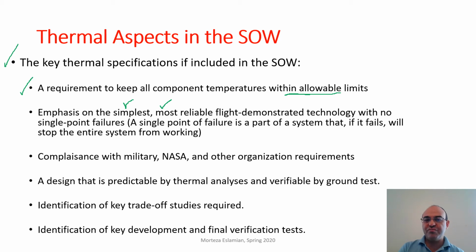So the document emphasizes that the contractor should design a thermal system in which no part of it is a single point of failure. Meaning that if, for instance, a part of the thermal system fails, it does not result in the failure of the entire spacecraft and entire mission. There should be a backup solution.